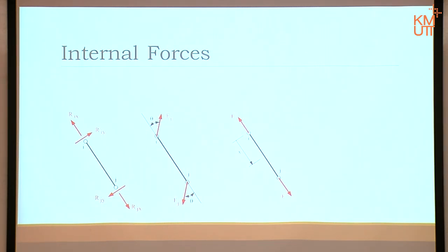Once we cut it, the usual picture we should see. Point I to where I cut, distance is x. At this moment in time, we don't know anything about internal forces in a pin joint truss. Well, let's assume we don't. So what happened here then? We have to assume full options here: three unknowns, the normal axial, the normal shear, and the bending moment. The special thing will happen after this.